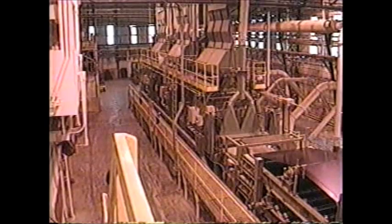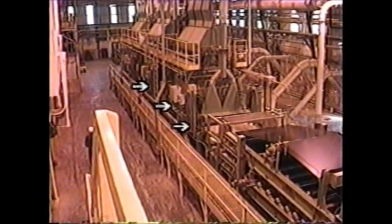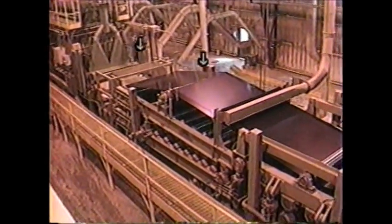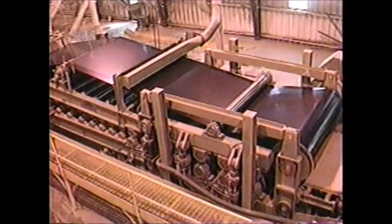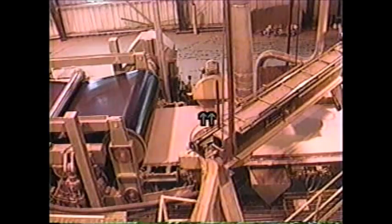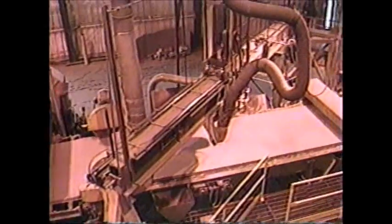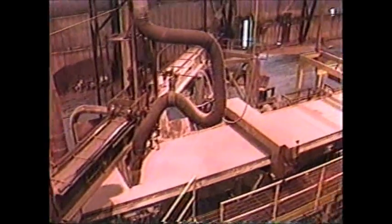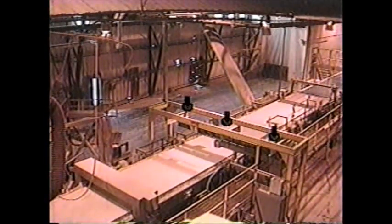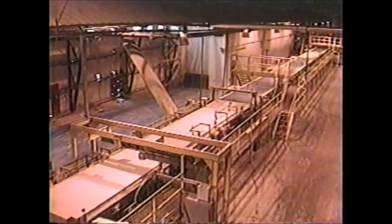We can get an overall look at the production line from our vantage point. First, we have the mat formers. Then a pre-press, which compresses the thick mat to ease handling. Then a trim saw, which trims the panel to width. Then a flying saw, which cuts panels to length. Then a moisture detector. Then a density monitor. Let's take a closer look at this end of the plant.